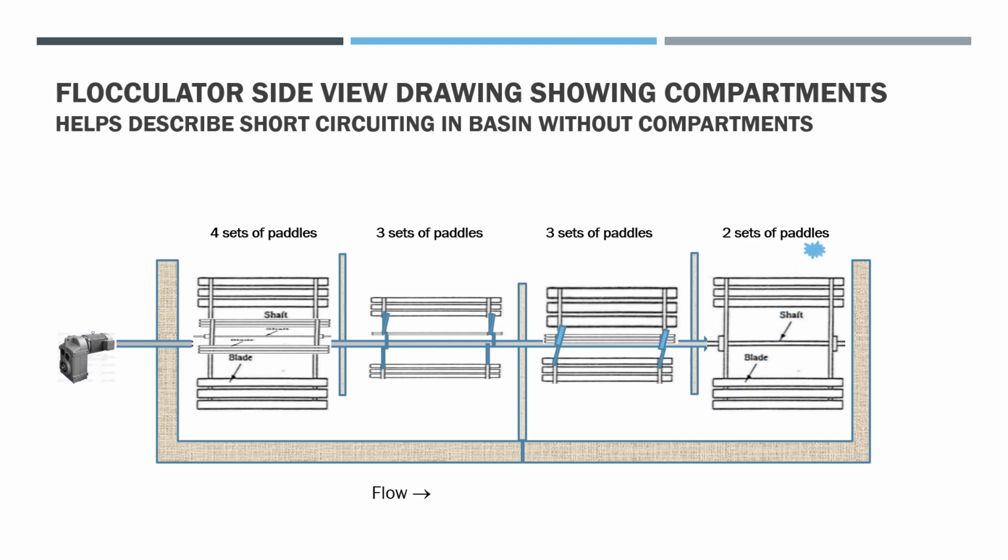In doing so, it has to take a more snake-like path, and so it travels a longer distance. By traveling a longer distance, more of it is forced into a plug flow arrangement, so more of it stays in there closer to the theoretical detention time of 30 minutes. There's less short circuiting, and that's what the engineer wants to design.